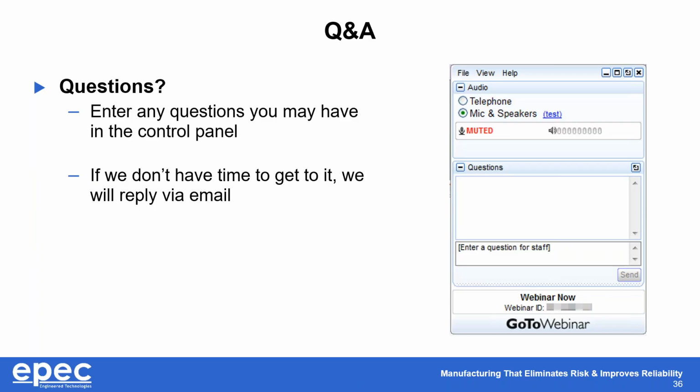Last question we can take here is, you mentioned that high pot is performed on 100% of production parts. Why not the other tests you mentioned? That's a great question. The answer, at least I have, would be that UL dictates that high pot is performed on 100% of production parts because it's a screening test to make sure that there's no manufacturing defects.